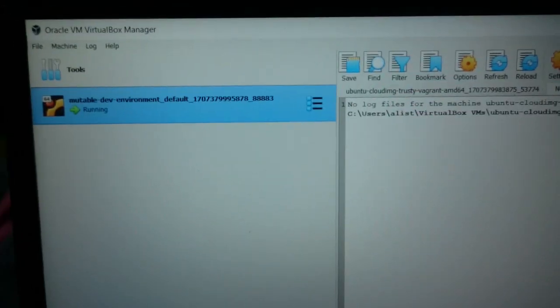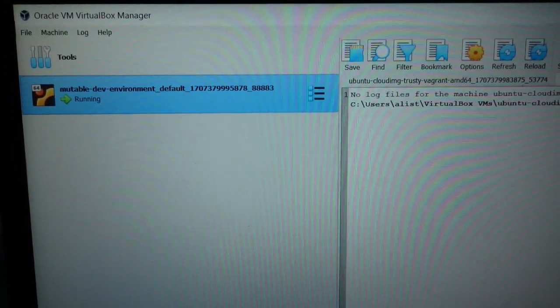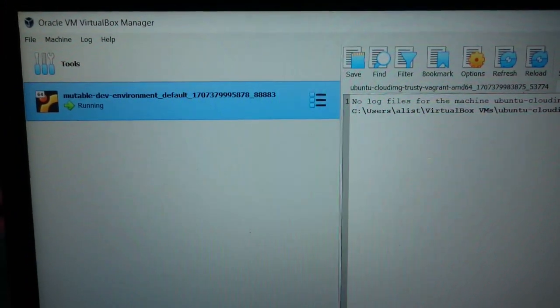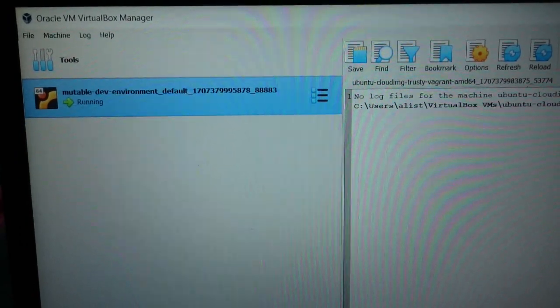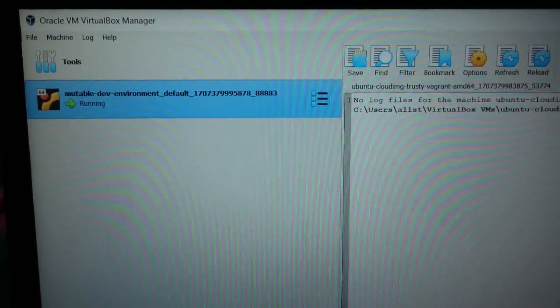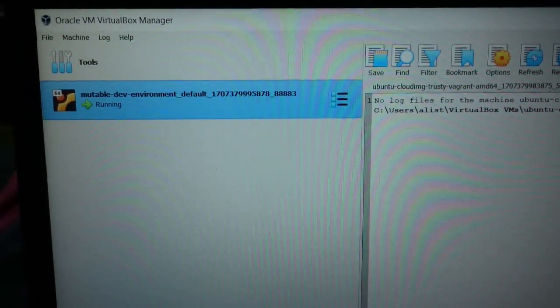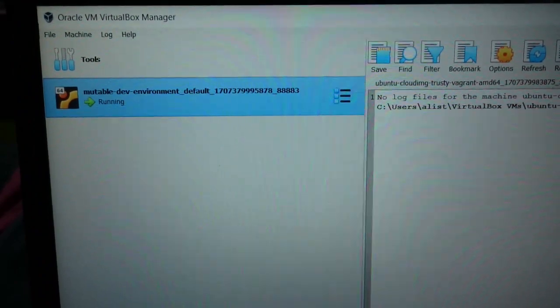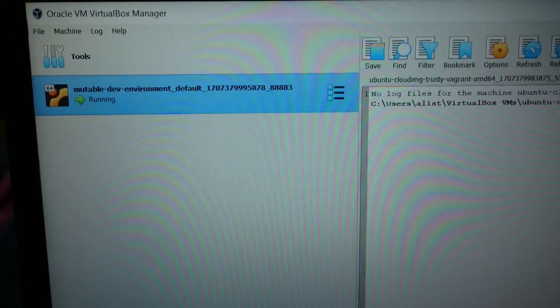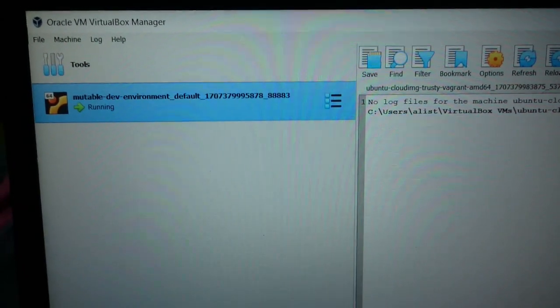So what do we need to do now? Well, for the ST Discovery board, which we were going to use as a programmer, you need to ensure you've got the appropriate drivers, and you can get those from STM on their website. That's the first thing. But clearly the virtual machine needs access to the USB connectivity on your laptop. So we're now going to check.